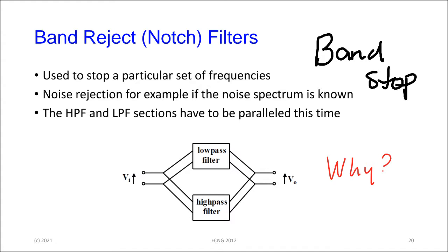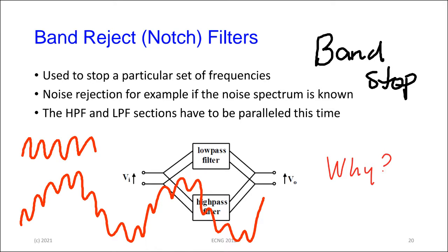And what you would get many times, if you look at small signals on a scope and you haven't shielded it properly, is that, let's say this is the signal that you want to see on the scope. Because of this 60 hertz interference, when you do it in the lab, you will get something looking like this, right? Where the signal is there, but in the background, it is riding on a 60 hertz signal. So here's a situation where the red is what you want, and the blue is what you want to get rid of.